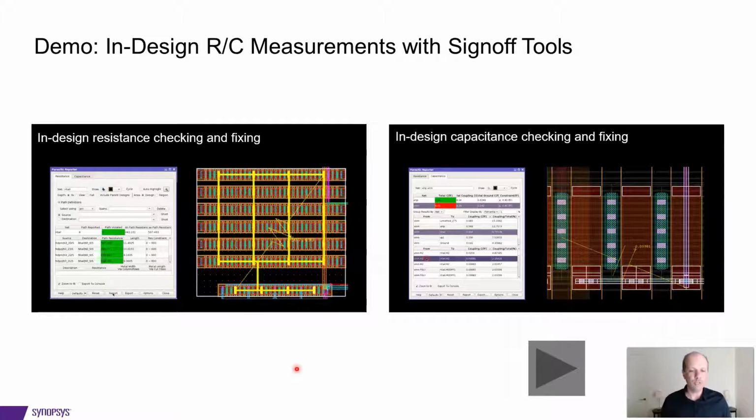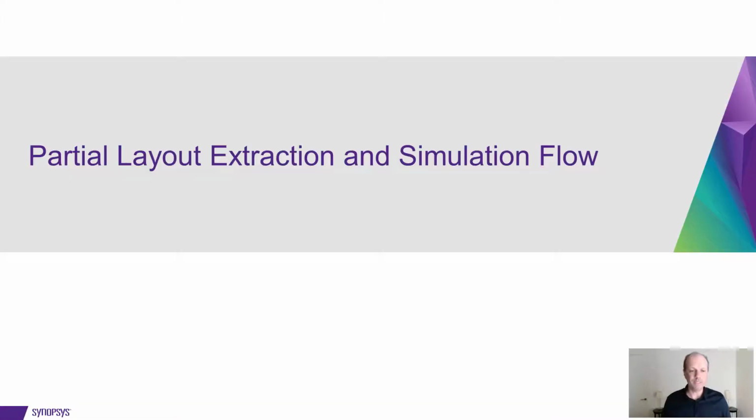I'd like to recap again. You've been able to see the parasitic estimation that helps close the gap between design and layout. Once you have a layout, you're able to update those parasitics. But how do you get to a wiring that honors the budget that was determined by the designer? You use a parasitic reporter, and that gives you a really powerful tool during your layout implementation to really optimize the wiring and nail down the wiring to honor the design intent.